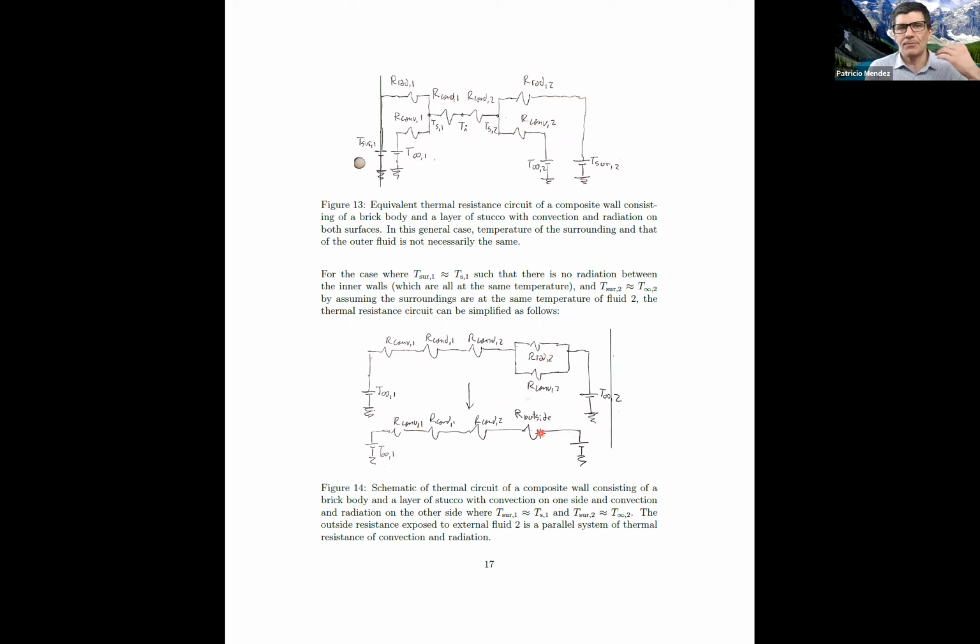And if you still have parallel mixed with series, mixed with parallel again, you keep going until you end up with a single equivalent resistor. In this case, it's very easy. I get this parallel circuit, and I move to here. Then I get this series circuit, and I'm done. This was a very simple problem, despite that it started looking like a spider web. That's the point of this class, that these things that look complex, we can deal with.